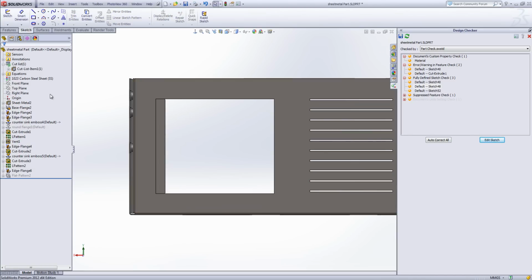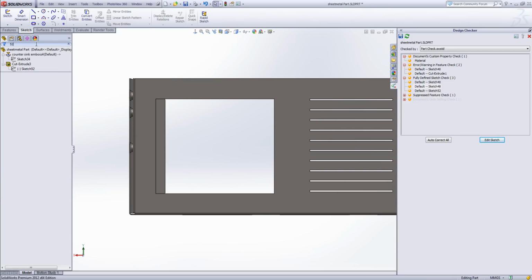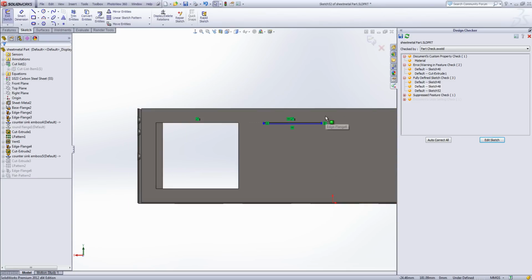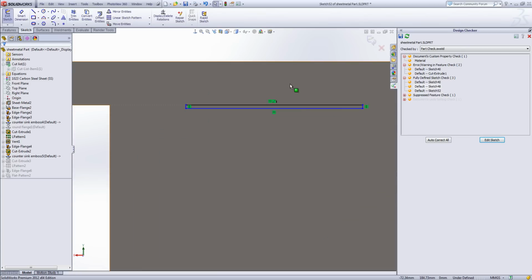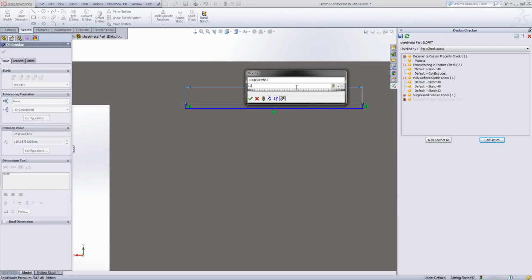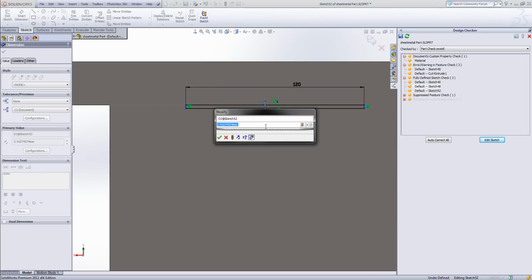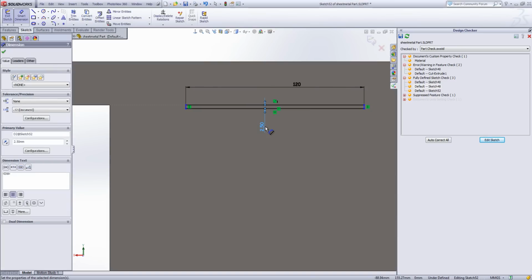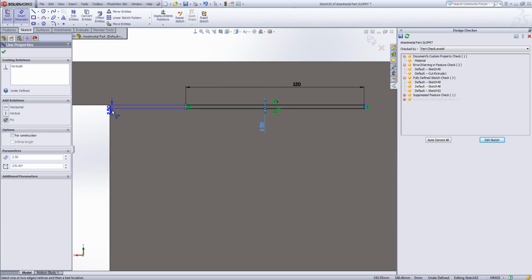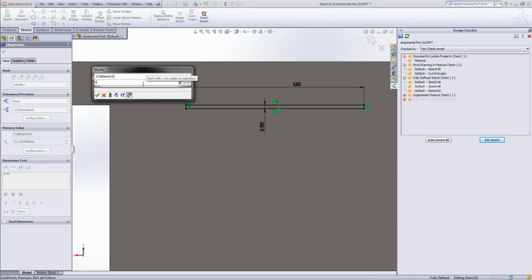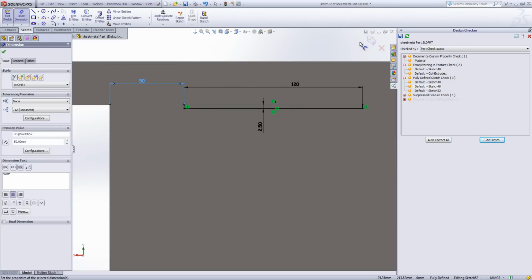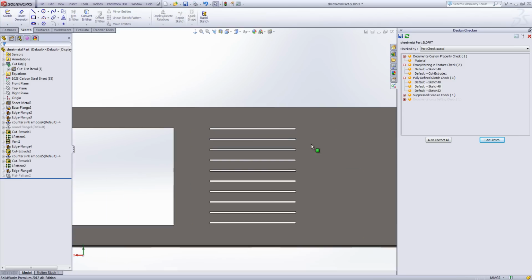I've also got sketch 52. Have a look for that one in the search bar. I can adjust this one and also add some dimensions in here to control the size. As I go through the design and add these in, the sketch will obviously become more and more defined. Okay, so that's fully defined this sketch now, and you'll see that's got rid of the problem.